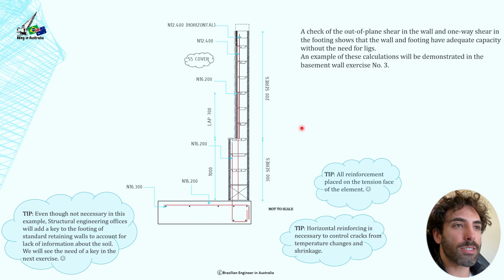I do cover these calculations in the ebook. So pretty much for this video, what you need to know is that these reinforcements are there to control cracks from temperature change and shrinkage. Another tip here: all reinforcement is placed on the tension face of the element.